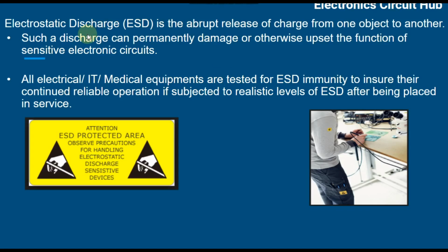So let us understand first what ESD is. ESD is an abrupt release of charges from one object to another object. Because of that, such a discharge can permanently damage or upset the function of a sensitive electronic circuit, right? All electrical, IT and medical equipment are tested for ESD immunity to ensure their continued reliable operation if subjected to a realistic level of ESD after being placed in service.